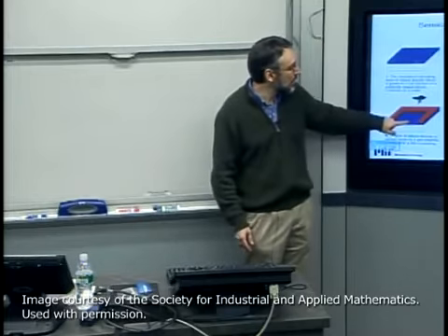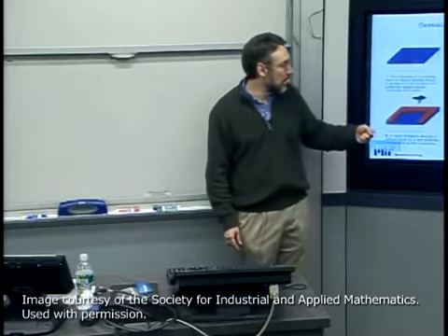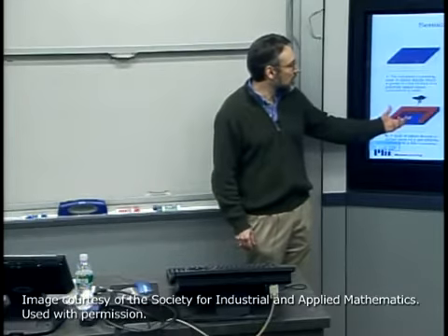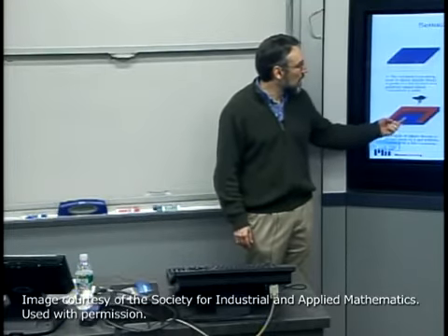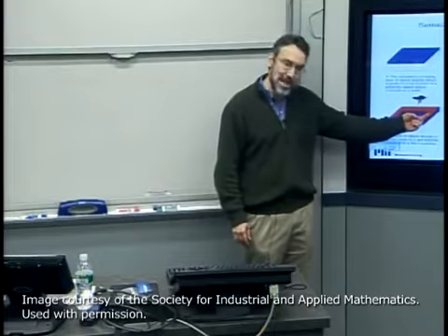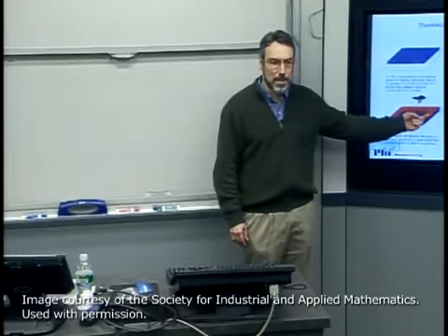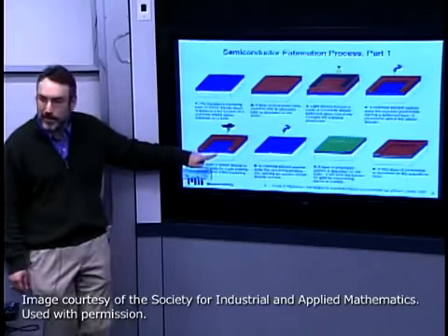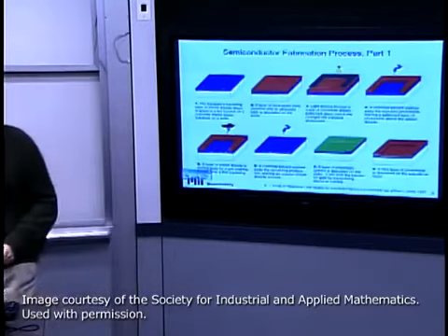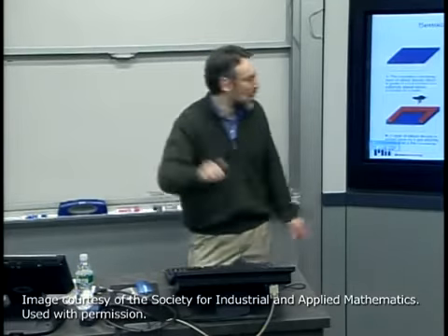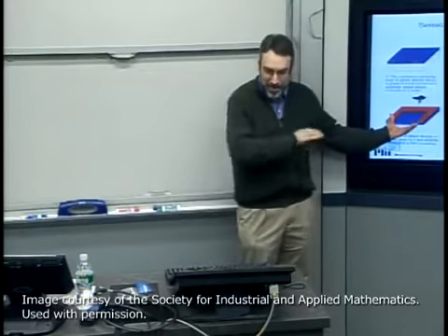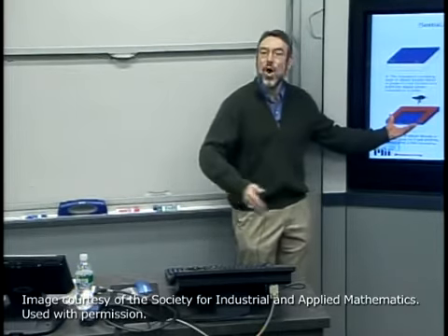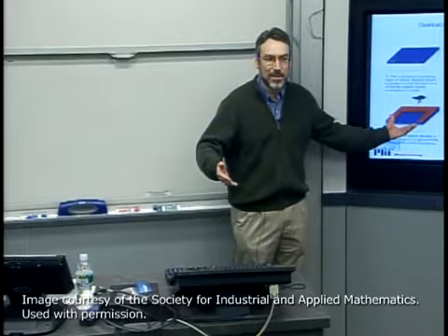The same idea I mentioned: we can choose an etch chemistry that allows us to etch silicon dioxide and not etch photoresist. We can also use one to etch silicon dioxide but not etch silicon. You can have very good selectivity so that one can stop controllably on the surface of the silicon. Now everybody knows exactly where they are across every place in the wafer. One can even over-etch a little bit, right?